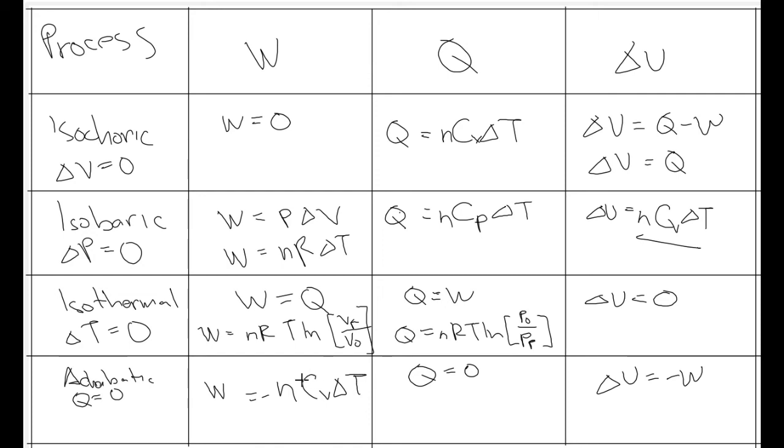So what happens to the temperature and pressure if the volume is constant? So if the volume is constant, as our temperature increases, our pressure increases, or we can rewrite this into an equation. So P1 over T1 is equals to P2 over T2.